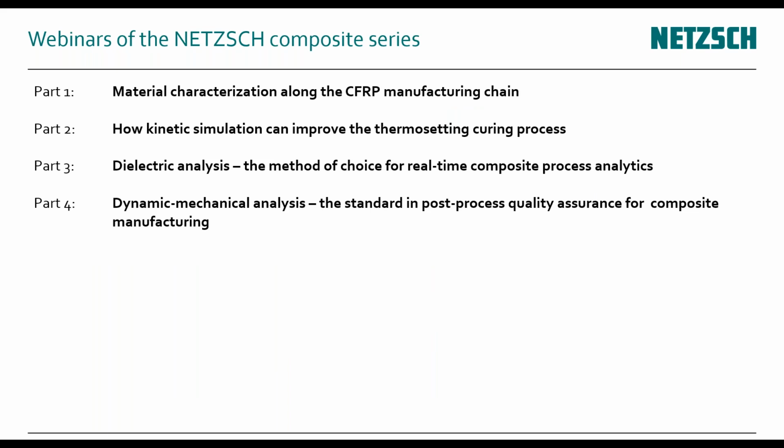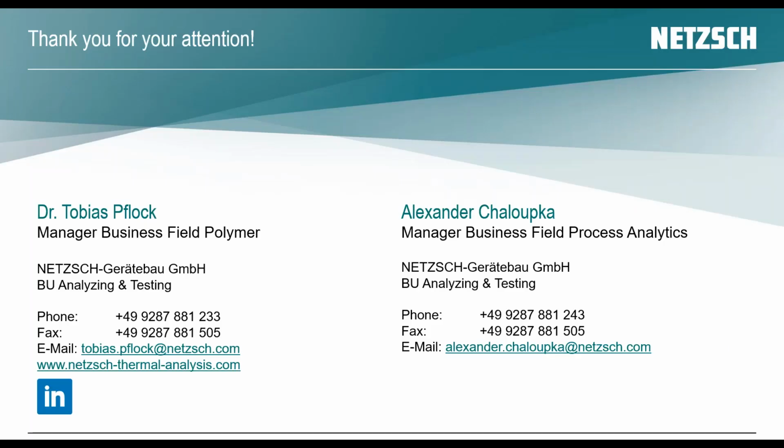Well, we tried to show you the whole picture of composite manufacturing and quality control related with that along the whole manufacturing chain, using kinetic simulation at the beginning, using the NETZSCH sensor as a process sensor during the process, and using the NETZSCH DMA Artemis, for example, for post-process quality assurance. With that, I thank you again for your attention.